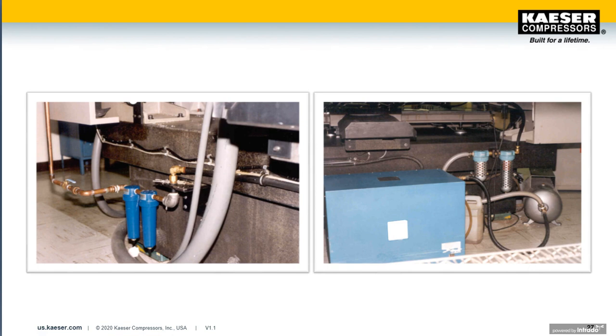Case in point here is the use of hard piping with full bore valves on the left versus the hose lines with the small IDs and barb fitting on the right. However, you will notice the point of use refrigerated air dryer, that's the blue box on the right side picture, along with the storage tank and filters.